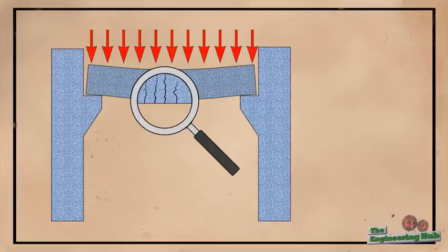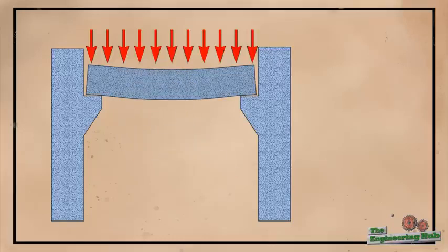In reality, even cracked concrete has some small tension resistance. However, using this strength is risky and unreliable. For that reason, engineers are forced to reinforce the section of the member that is expected to experience tension. For simple beams, as we saw earlier, this is always the bottom side.